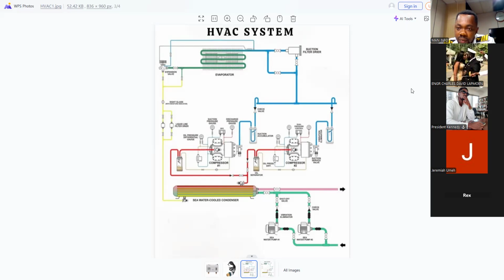My question is, you displayed two compressors, one for residential and one for industrial. For the residential one, if there's no space where you can see a leakage, like the floor or a base that displays the leakage of the oil, how do you know the oil is short? How do you identify a leakage? And how do you know the system is short of lubrication oil?